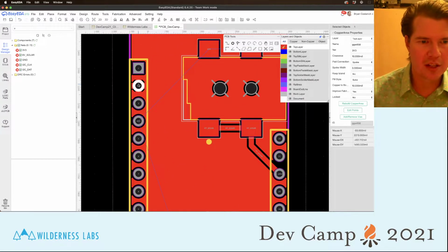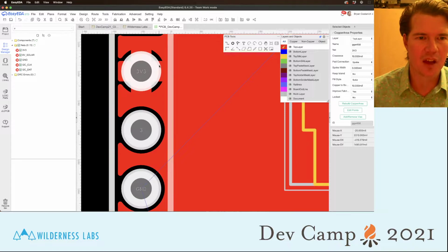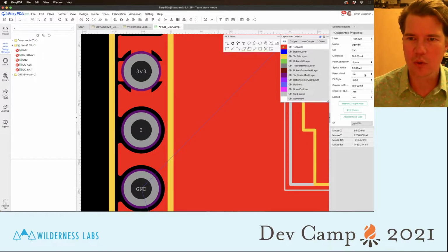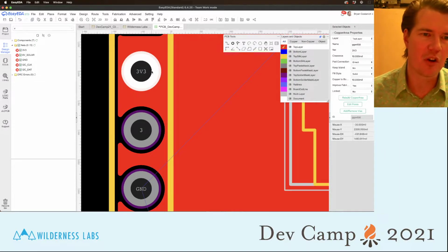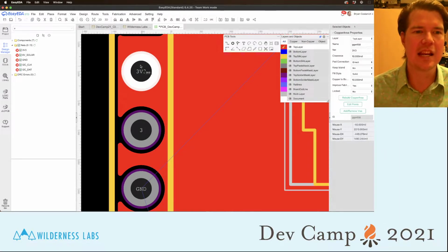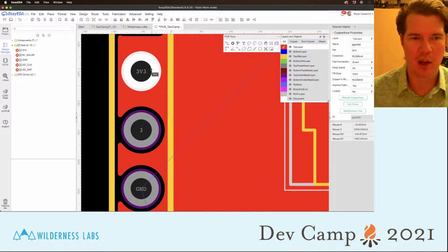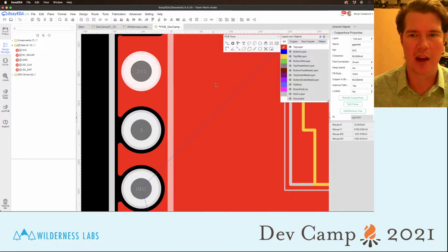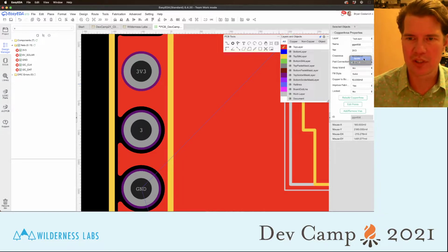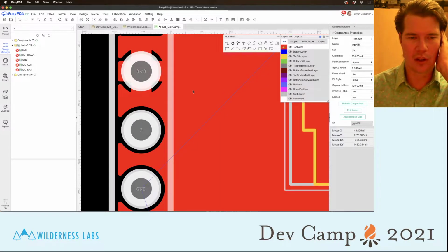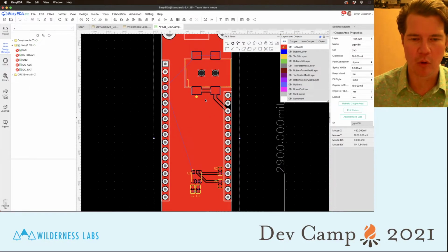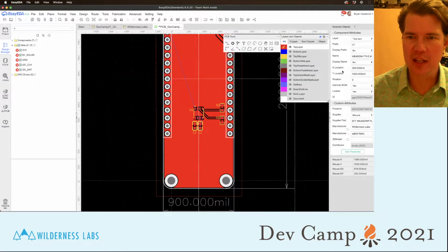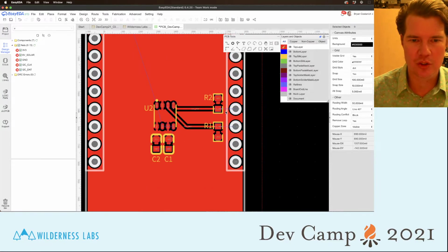It also makes it easier to solder. For example, let's say we were actually having to hand solder this. If this were a direct pad connection, it would be very difficult with a soldering iron to heat this up enough to actually get solder to melt, because all the heat would just be flowing out into the copper pour. So we want a spoke or thermal connection. The other thing is islands, and we'll show that in a sec.